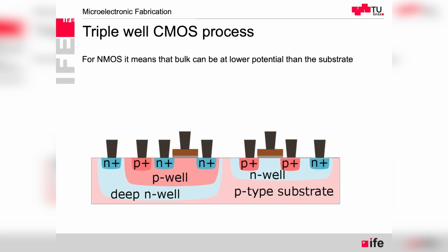So normally, when we talk about CMOS, the PMOS and NMOS transistors, we had them in P-type substrate. And the P-type substrate at the same time was bulk for the NMOS transistor. Imagine if we have lots of NMOS transistors, and for some reason, to adjust the threshold, we would like to change the bulk source voltage. We would change it for all the transistors. That might be the motivation for digital circuits, that it would be okay to change for all the transistors. It's rarely done, but that's a possibility.